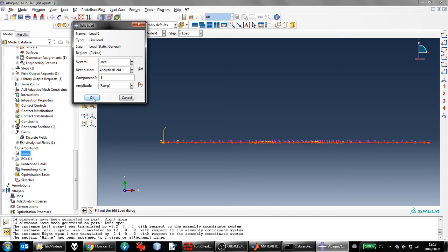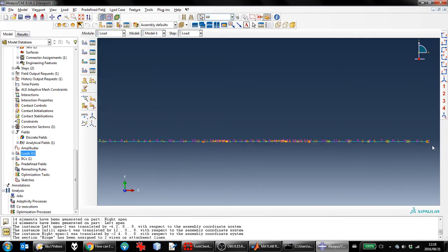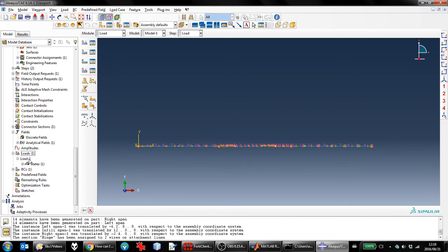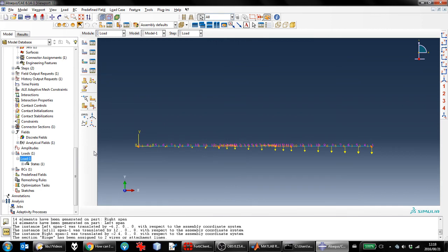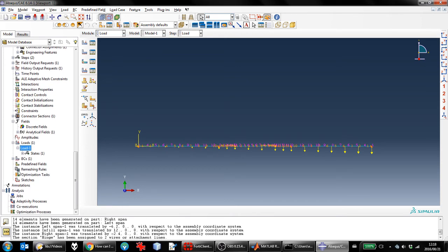Right, so if we do that, you'll see that it only shows little squares as the load gets bigger from the very left end of the bridge. If we go back to our load definition, you can then switch on here that you want to see it in the global coordinate system. You'll see there's no component Y there now. And it does show us the correct triangular distribution. So the two things are equivalent, obviously, because the global and local coordinate systems coincide in this case.